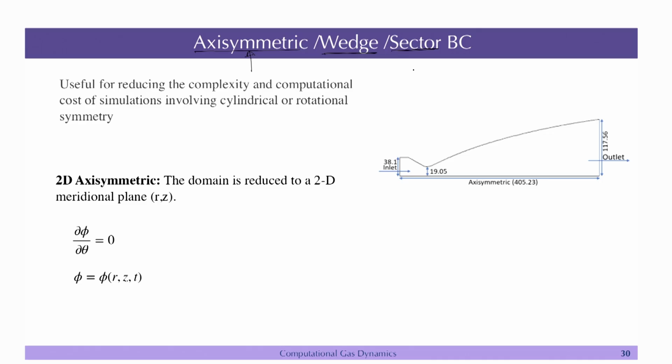Let us say you have a nozzle. This is one of the shapes of the nozzle that I am talking about. This would have been my nozzle, and now you imagine this in 3D. Basically it is rotated like this. Around this axis it is a 360 degree nozzle. You would expect that the flow is coming in at a 0 degree angle. If you take any plane in the azimuthal direction, you will have the same flow, in the mean sense.